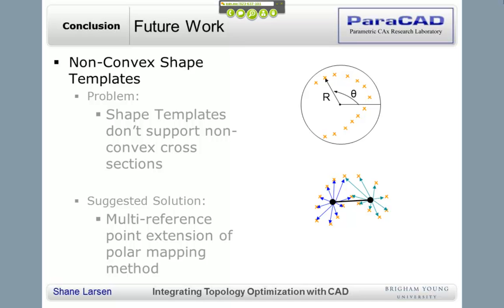It's all dimensionless. So if you're putting your model in using inches, and you've described the thing as being 10 inches long, then the load that you're going to be wanting to work with is going to be English units, not metric. Okay, and so it is unitless. You just have to remember to work out the units as you're putting them in. Okay, and just be consistent.